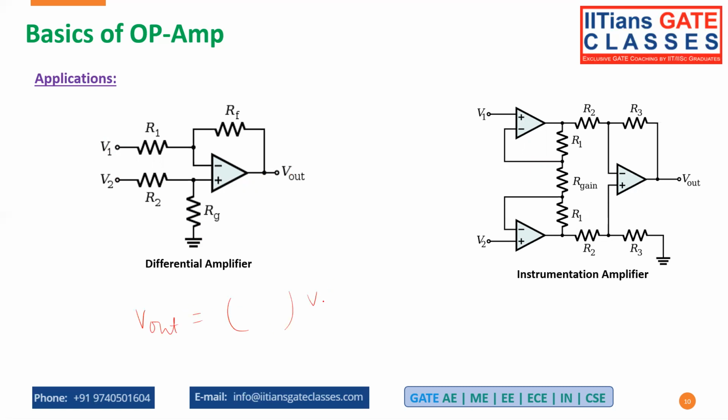You can derive this also. And the instrumentation amplifier, you can also derive that. If you derive that, you will understand how the signal is getting transmitted, if you're applying it to the positive input, how the signal is getting transmitted to the output terminal. You see, there is no current inside the op amp. This is the very basic fundamental rule, or I can say the principle of the op amp, that there is no current inside the op amp. So whatever current is coming from here will go to the output. That's why you're getting the output here, right?